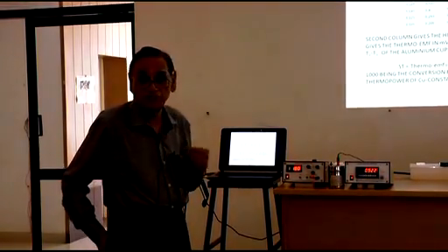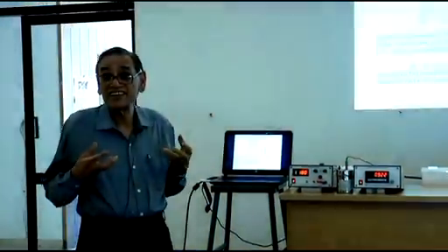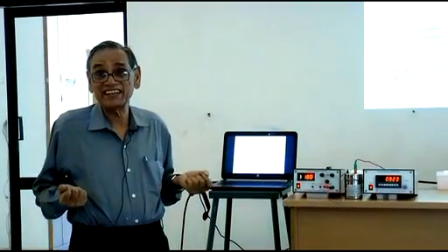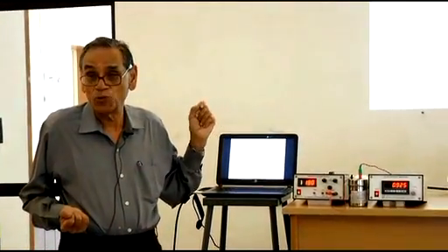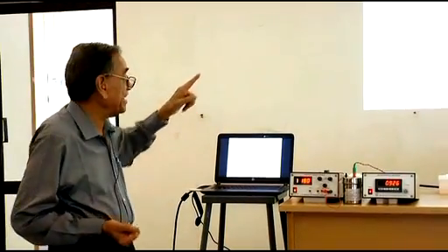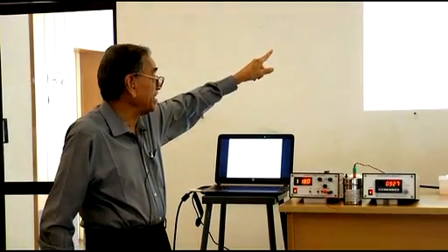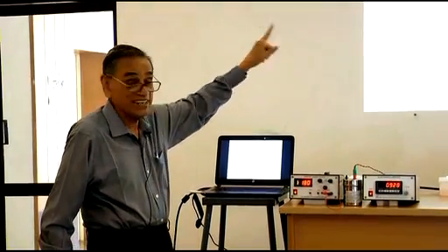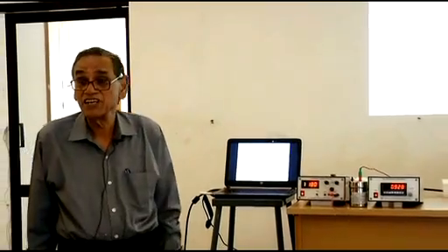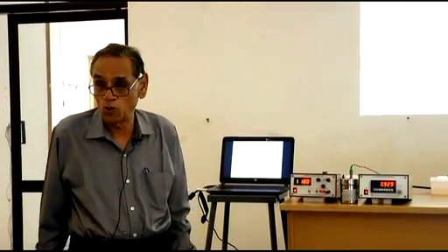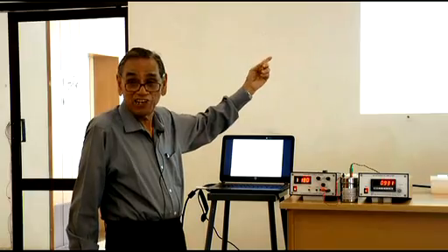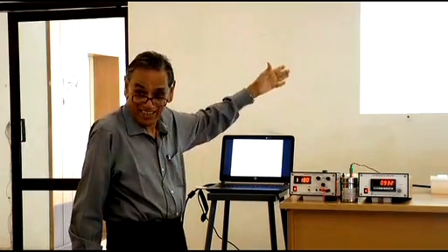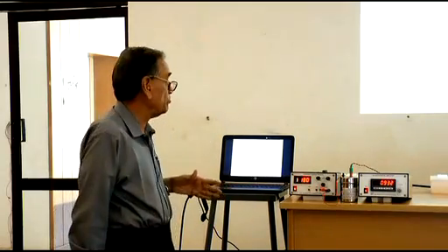The second column gives you the heat generated in the resistance per unit time, Q in watts. That is obtained by taking the square of the current, multiplying it by the resistance of 20.1 ohm. So you start with a maximum heat input of 0.8 watt and then you reduce the heat input.